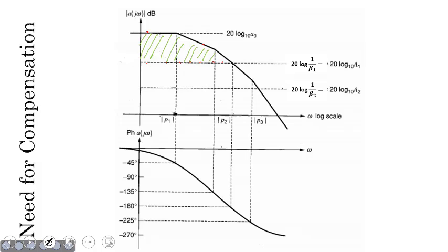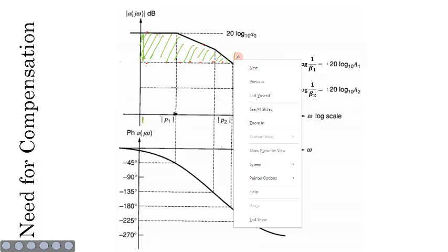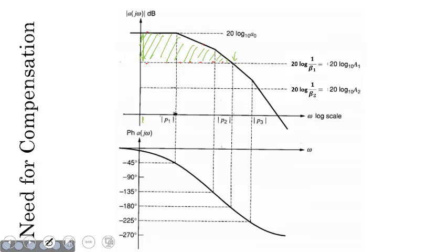When we are at a frequency of 0 hertz or 0 radians, we have a loop gain magnitude which has this value. Now there is a frequency known as the gain crossover frequency. It is the frequency at which the loop gain magnitude becomes 0 dB, or becomes 1, and this is termed omega gx. When the phase value is greater than minus 180 degrees at omega equals omega gx, then we say that the system is stable, correct?